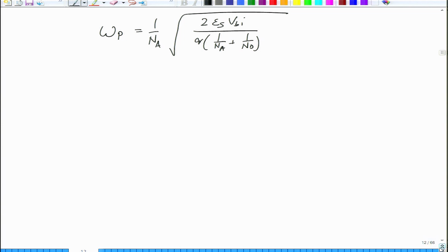So, we have got two expressions for Wn and Wp. So, we know that capital W is the depletion region width. So, W is equal to, what is it? Wn minus of minus Wp, all right. So, basically it is Wn plus Wp.